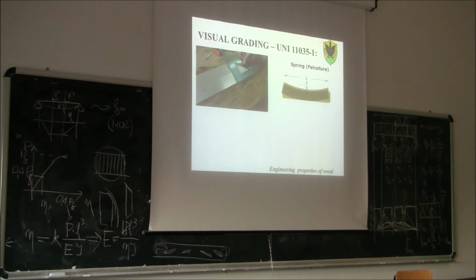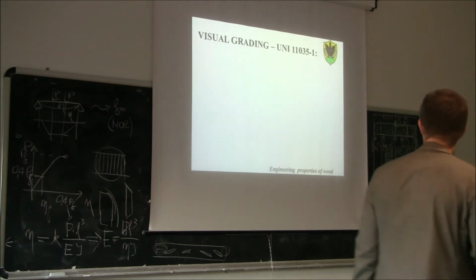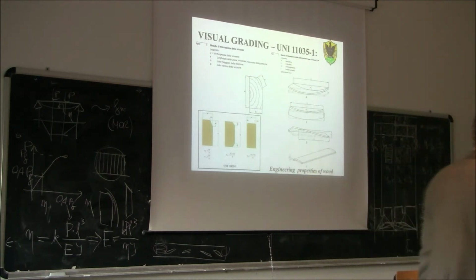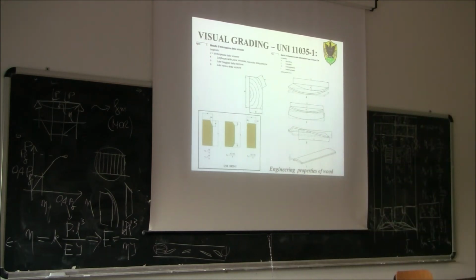These distortions are basically due to the fact that when we cut the wood, initially the wood has lots of humidity inside, and then the wood is going to shrink because the humidity is going to be lost over time. We will see it better later on. You will go from, for example, 100% of humidity, which means that the wood is more water than material, basically, down to a situation where the moisture content will drop to 12%.